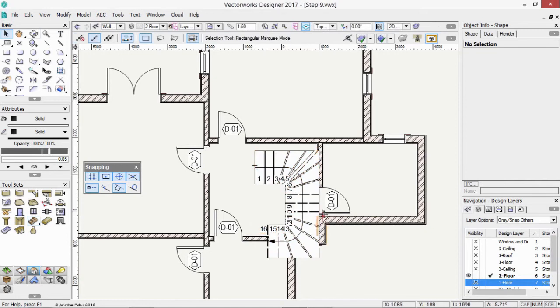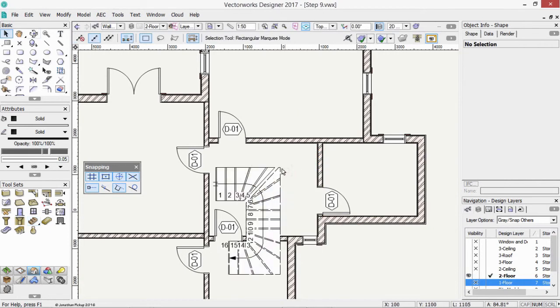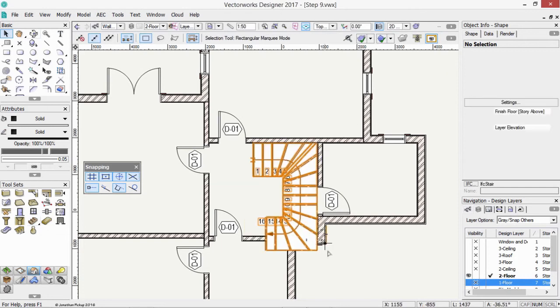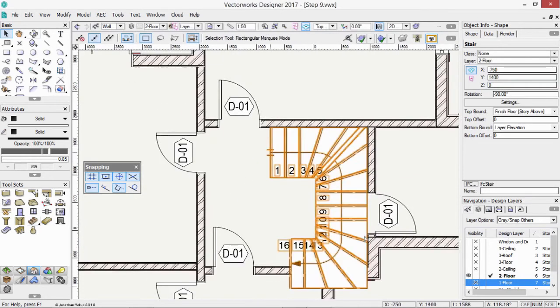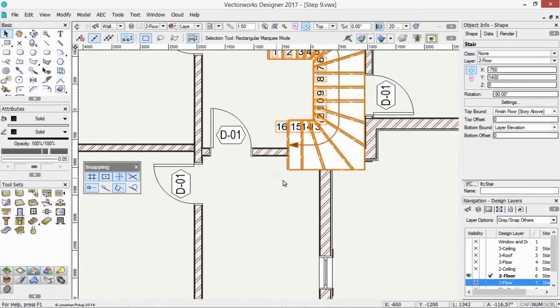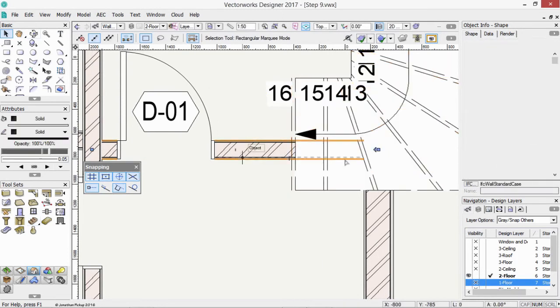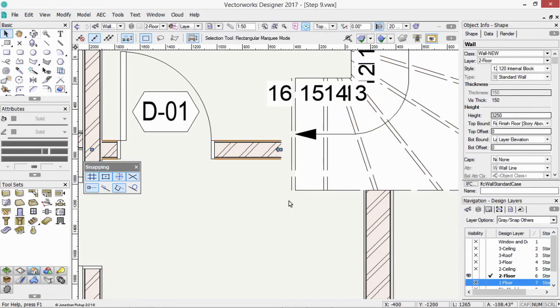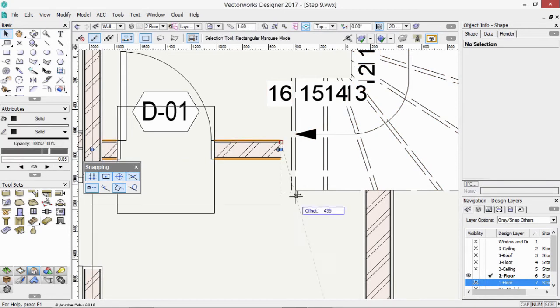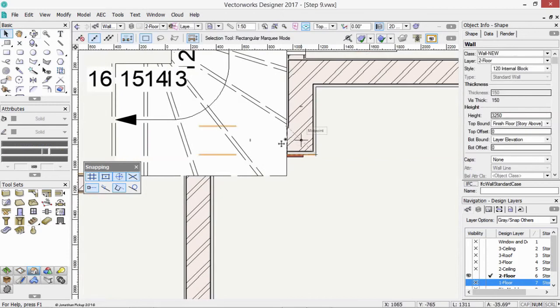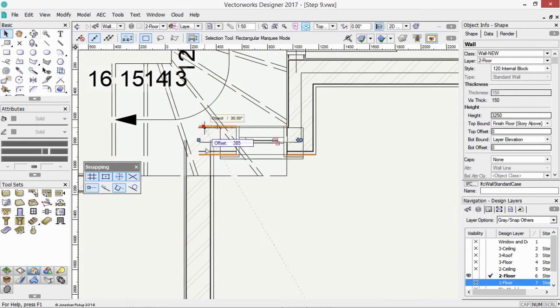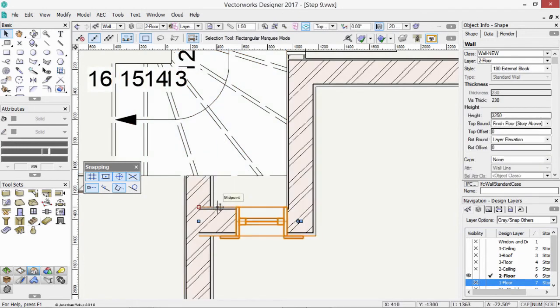So we'll notice that at this point we could perhaps put that stair here, drag that into the corner, but now you'll notice that in order to get that stair to go up, we need to move this wall down. So we're going to have to do a bit of moving. So we could grab hold of that, pull that down to there, but you notice because I had that wall joined, it didn't like to move it. So let's just move that wall to there, and then I can drag that wall down, touch that point. And there's another wall under here. So let's hold down the B key, maybe will allow us to grab that wall and pull that wall down. And we're just going to drag that up till it touches the stair.